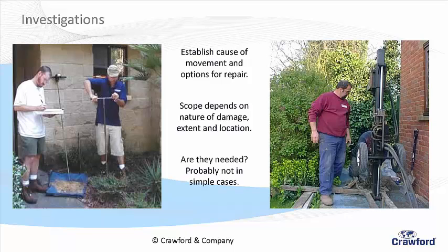So we end up having to do things like mechanical augers, which is this piece of equipment on the right, which takes, if you want, the elbow grease out of that one. But you don't really want to turn up on site and take that through someone's kitchen. So you need to make sure you've got access. Another system we use is window sampling, but it's all a mechanical way of driving an auger through to get the sample we need. We absolutely need to have that.